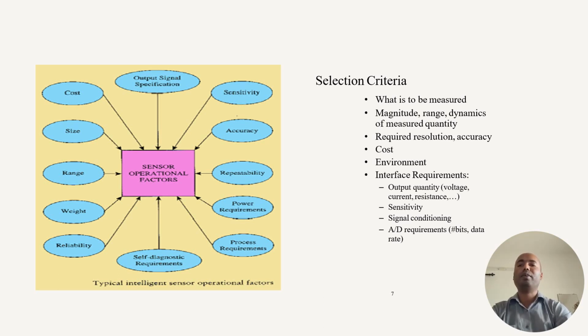Then power requirement of the sensors. Some of the sensors require DC power, some work on AC power. Some of them work on less than 12 volt power supply, and some of them require more than 12 volt power supply. For that, stepping up actions are required. And in the special case, some sensors don't require power for working.